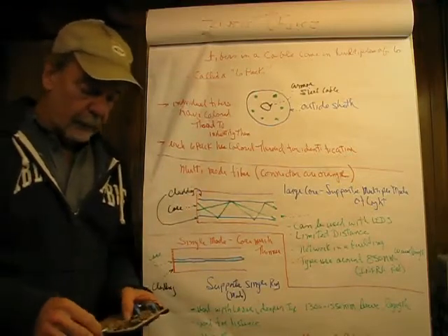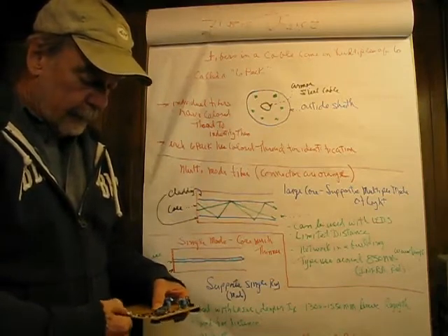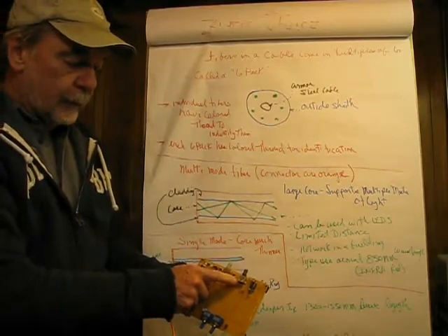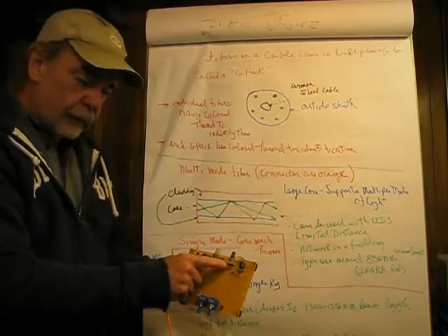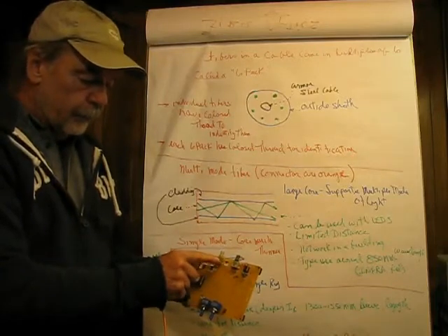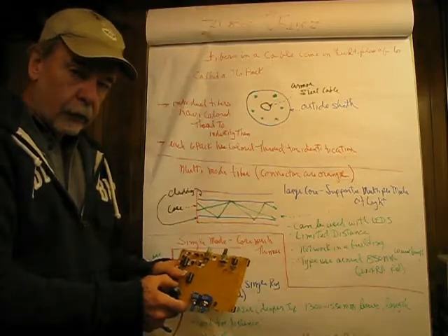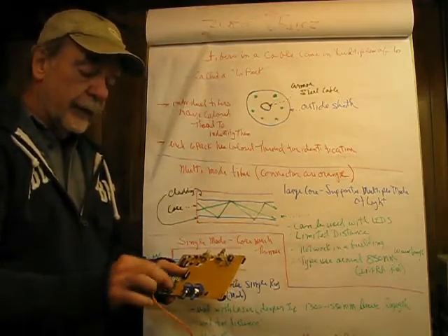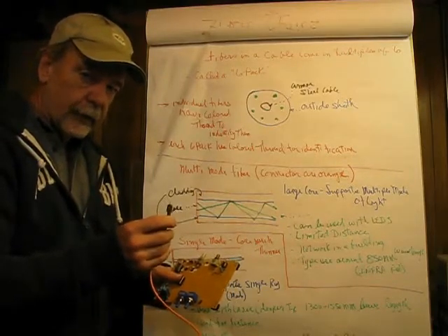Now, this here is an optic trainer I was starting to build, and this here is a fiber optic LED. Its launch power is negative 12 dBm to negative 16 dBm. This is the receiver. These cost about $21 a piece, and they're designed using a commercial grade ST connector. Now, there's a whole bunch of different connectors.